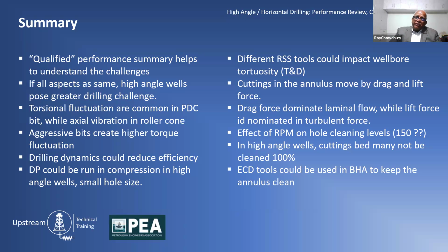They do not want too much engagement of the roller reamer with the well, because there is still a concern that with too much engagement between the reamer and the wellbore, you might leave the rollers in the hole. So it is always recommended that you have a roller reamer which is at least 1/16th under gauge.